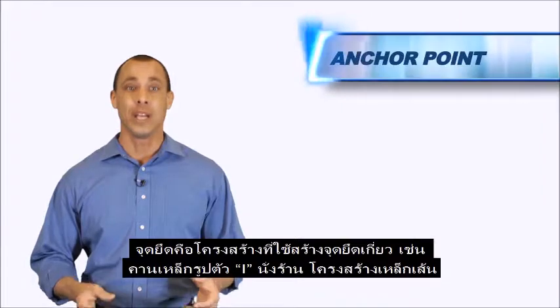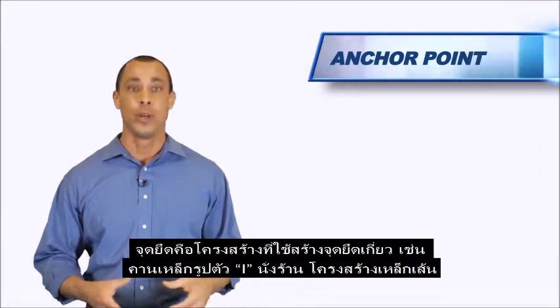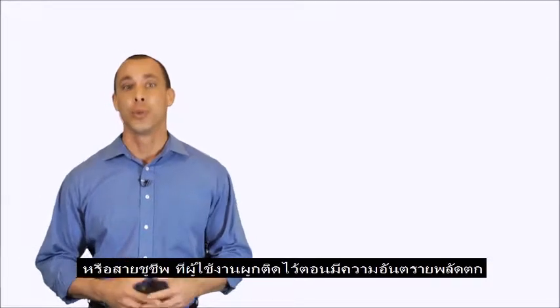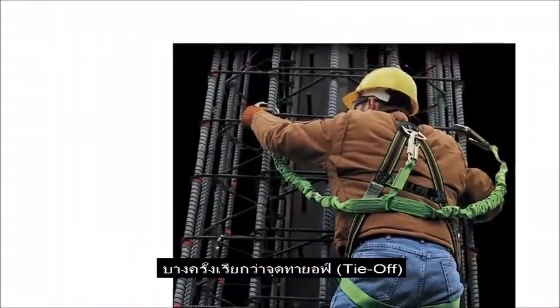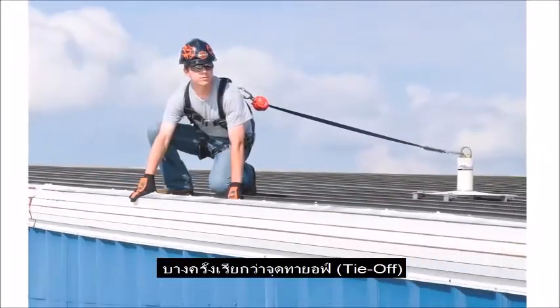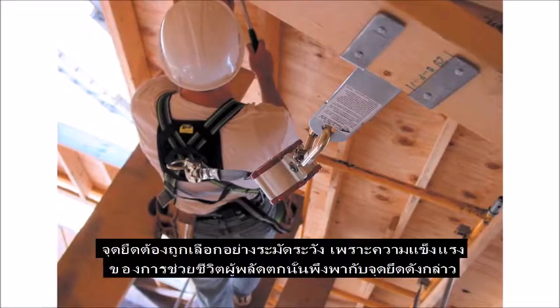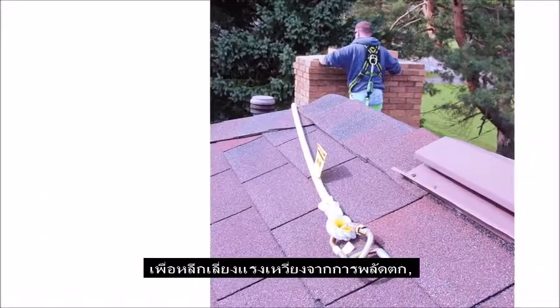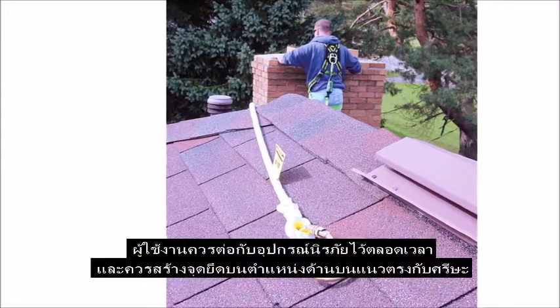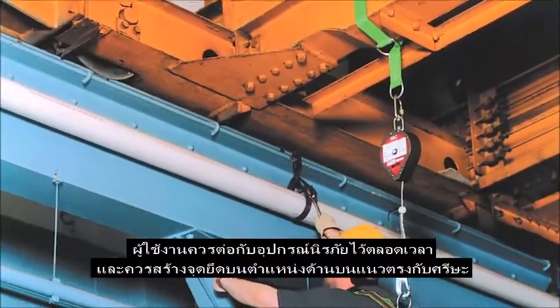An anchor point is a structural item such as an I-beam, scaffold, rebar, or lifeline to which workers are affixed when a fall hazard is present. It is sometimes referred to as a tie-off point. Anchor points must be carefully selected since workers depend on their strength and stability in case of a fall. To avoid a dangerous swing fall, workers should always try to connect and work directly underneath an anchorage point whenever